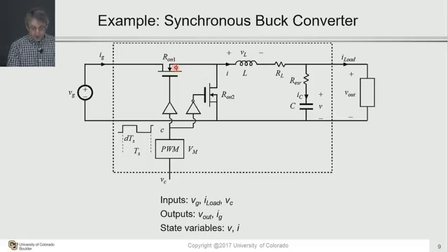So normally in a buck converter, we have the main control switch and the rectifying diode right here, right? The diode would be pointing here. And you could just as well have a single controllable switch with a rectifying diode performing the function of the single pole double throw switch in the buck converter. That's perfectly fine.